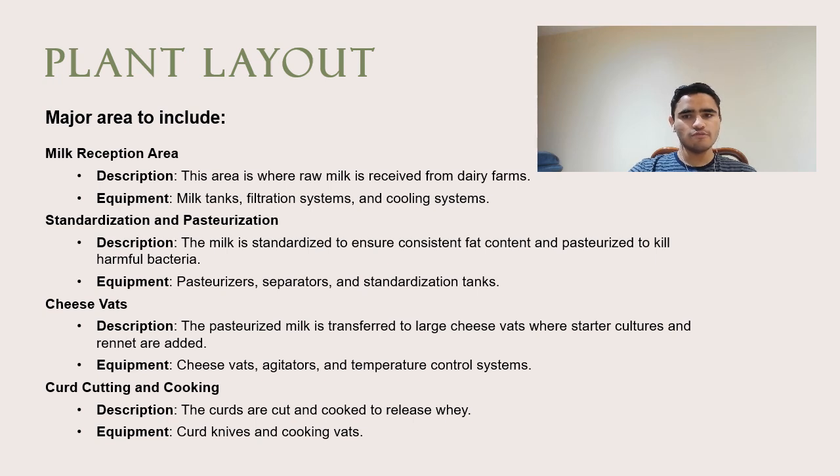And the next stage will be the curd washing and draining area. After the curd has been processed, it is stored there, and after that there is a washing area inside that secondary plant hall where the curds are washed to remove excess whey and lactose, which helps improve the cheese texture and flavor. Draining tables and a specialized washing system are also located in this area. That is the whey processing and boiler area. There is also refrigeration and storage included in case anything goes wrong, so we have a backup over there.